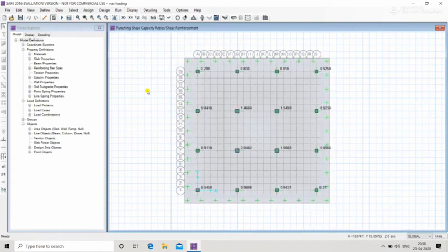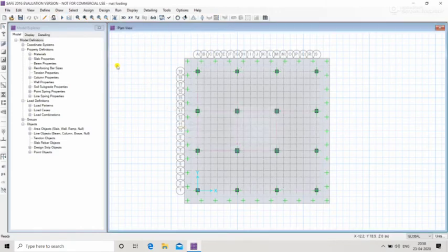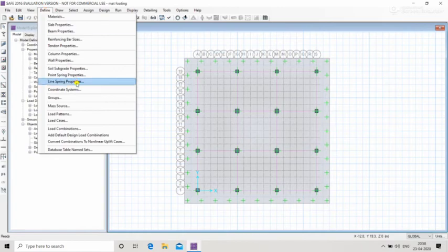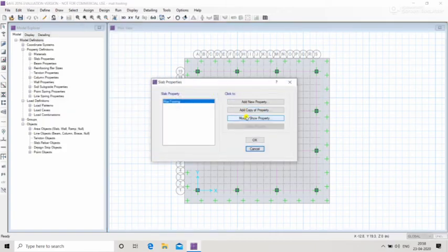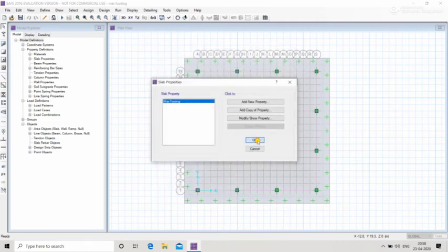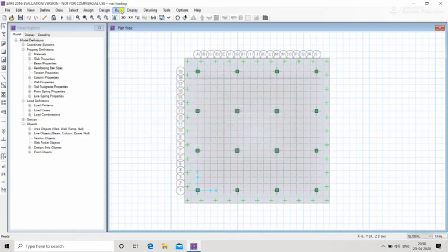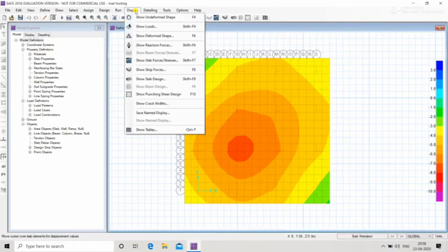In that, click on detailing and then expand slab views, and by clicking rebar schedule bill of quantities, you get the details of all the quantities required for the design and the number of bar and the length of the bar to be cut, etc. We can go through each and every option on that, so that you may get the different plan view and elevation view of the foundation. The detailed representation is shown on the screen.